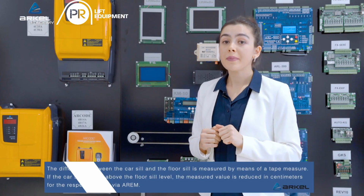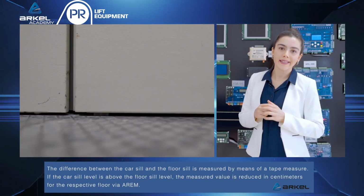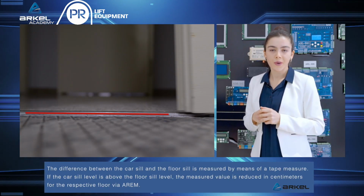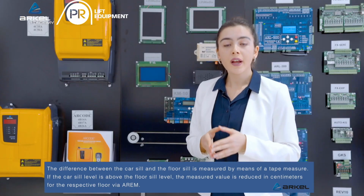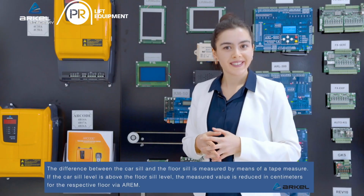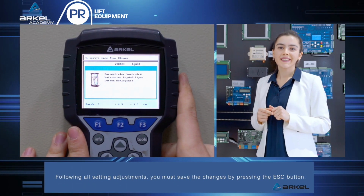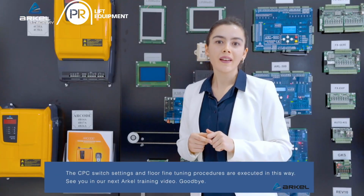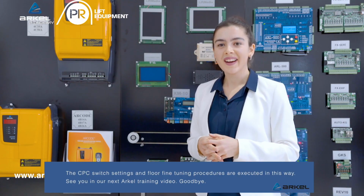The car will not move during this procedure. The settings made will be effective upon the arrival to the relevant floor next time. This fine-tuning should be made from top to bottom and from bottom to top for all floors. Following all setting adjustments, you must save the changes by pressing the ESC button. The CPC switch settings and floor fine-tuning procedures are executed in this way.